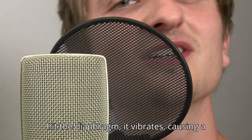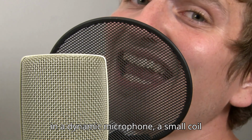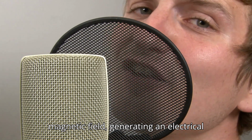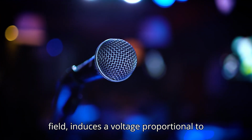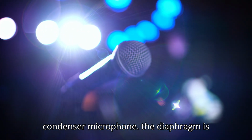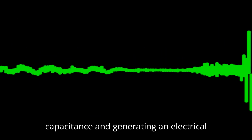When sound waves hit the diaphragm, it vibrates, causing a corresponding change in a magnetic field or electrical capacitance. For instance, in a dynamic microphone, a small coil attached to the diaphragm moves within a magnetic field, generating an electrical current through electromagnetic induction. The movement of the coil in the magnetic field induces a voltage proportional to the sound wave's pressure changes. In a condenser microphone, the diaphragm is placed very close to a backplate, forming a capacitor. Sound waves cause the diaphragm to move, changing the capacitance and generating an electrical signal that corresponds to the sound